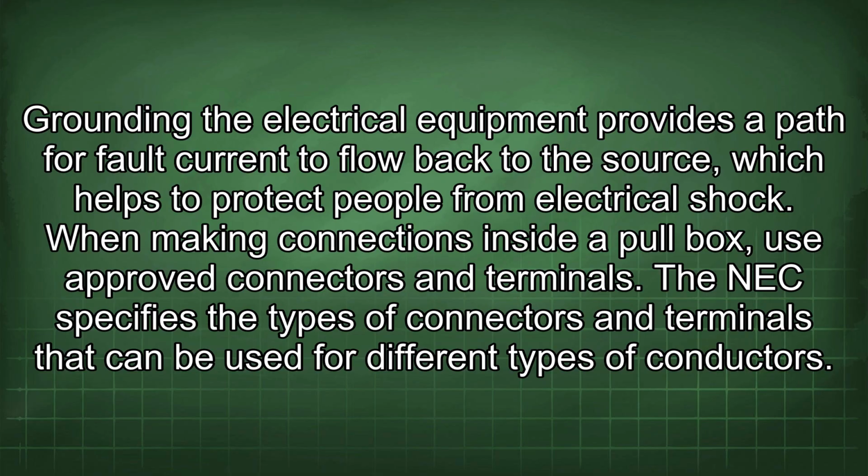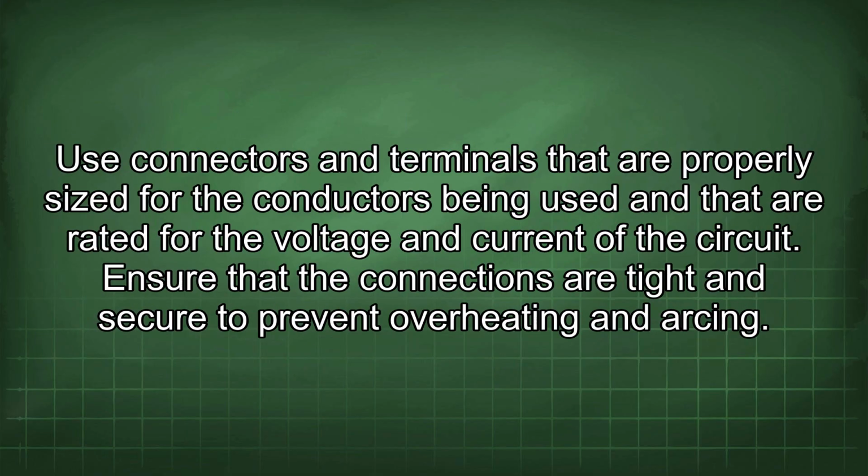The NEC specifies the types of connectors and terminals that can be used for different types of conductors. Use connectors and terminals that are properly sized for the conductors being used and that are rated for the voltage and current of the circuit. Ensure that the connections are tight and secure to prevent overheating and arcing.